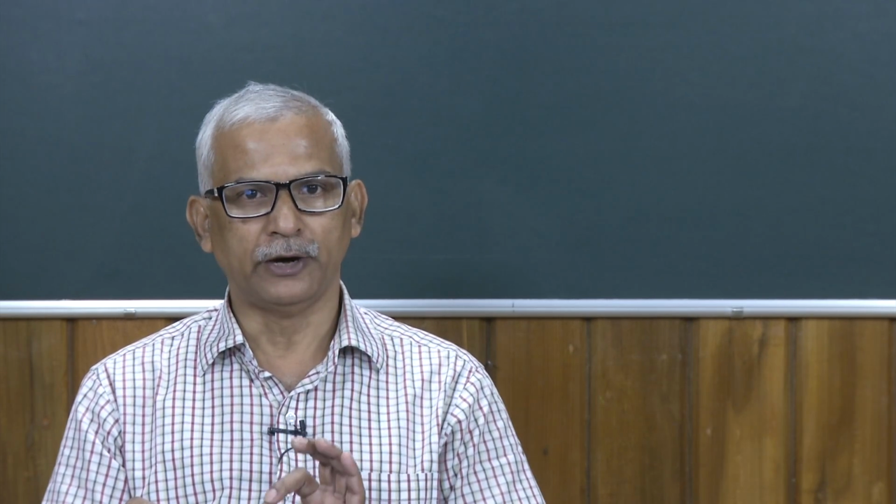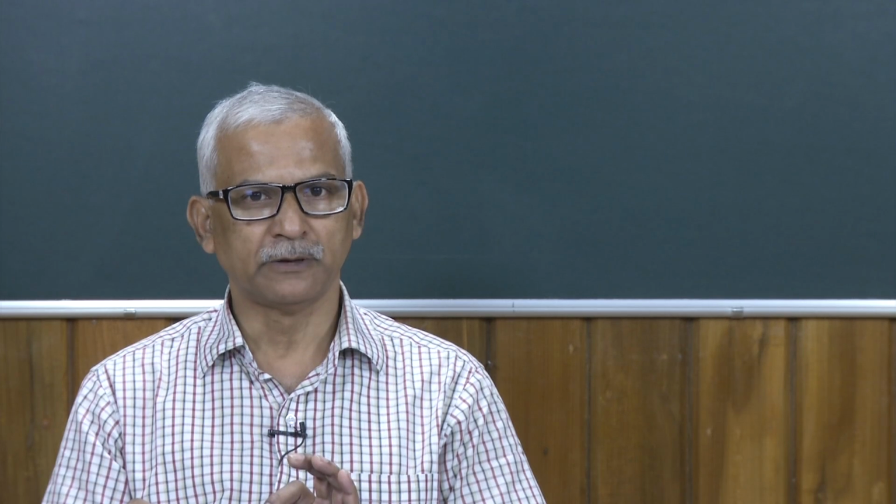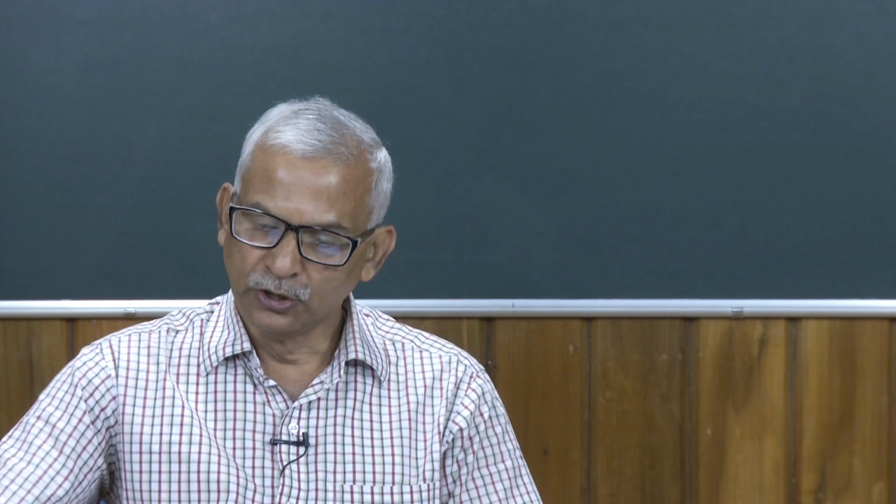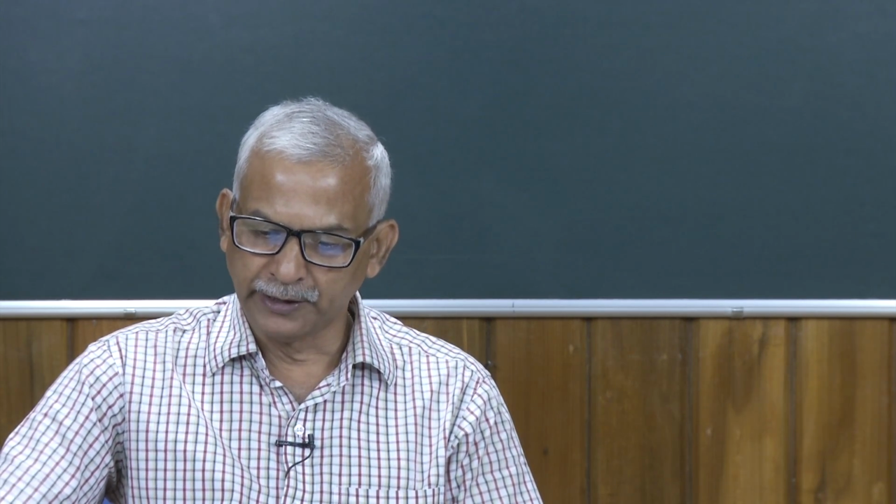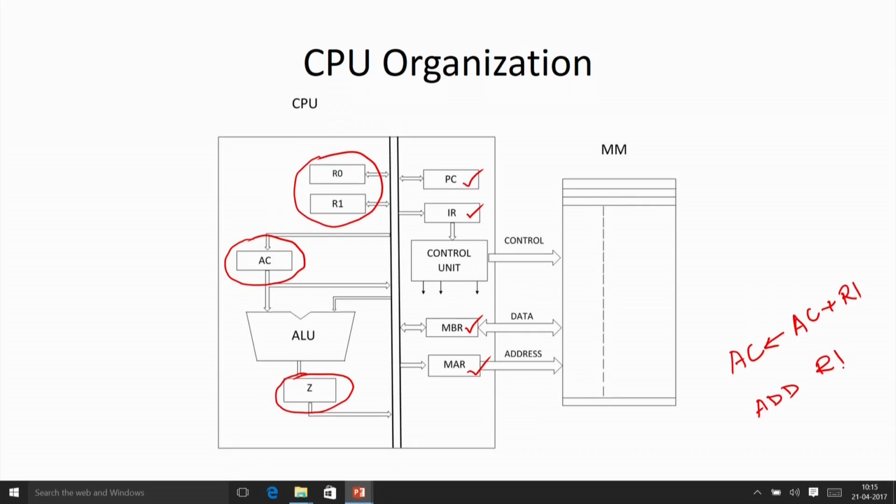So, one of the registers is implicit over here. That means to perform this operation I can simply write ADD R1. In that case, what will happen? Take the contents from register R1 and add them to some number. To which number are we going to add? Whatever number we have in the accumulator, we add R1 to that accumulator and store the result back into the accumulator. So, this is the effect. We have to specify only one operand over here. So, this is your accumulator.